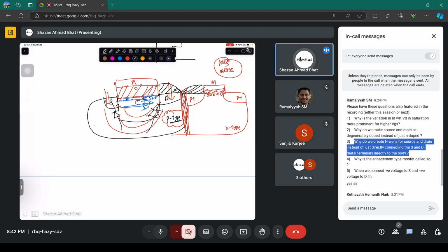That is another reason why you make these pockets, which are just highly doped pockets in the same substrate. You don't connect a different source or drain to this region. These are the same part of the substrate, and you do ion implantation.